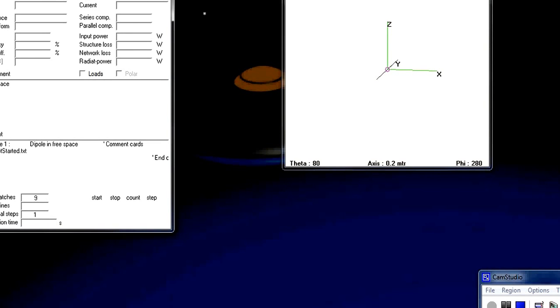All these are greyed out. Now the reason they're greyed out is because we haven't actually calculated the characteristics of this particular example antenna yet, but we'll come to that. Now this is the calculate button. Now this button you will use all the time. It will allow you to calculate the far field, near field, frequency sweep, and all sorts of other things. So just keep that in mind. Let's now have a look at some of these grey buttons by pressing the calculate button.